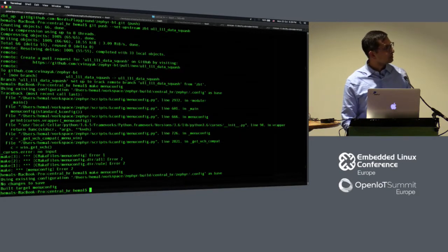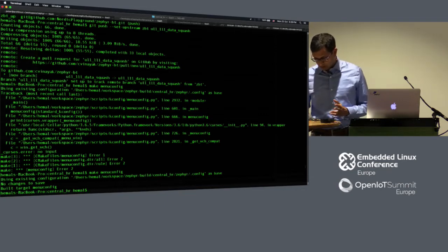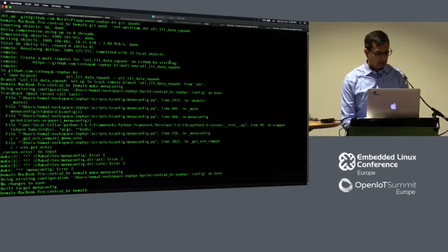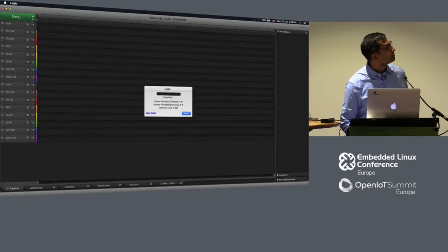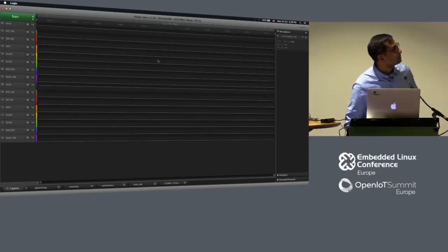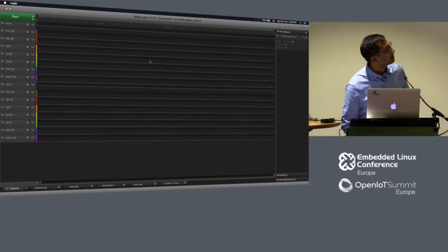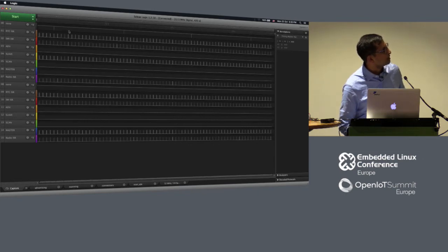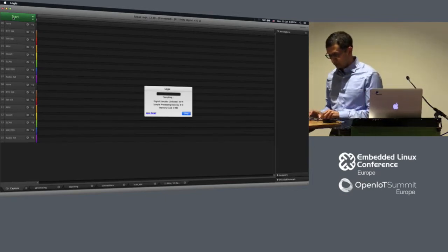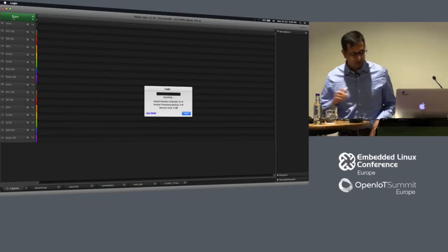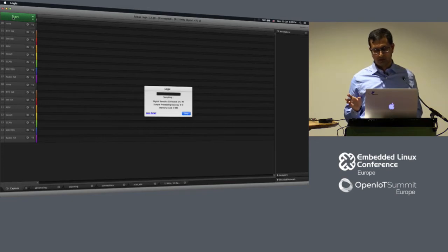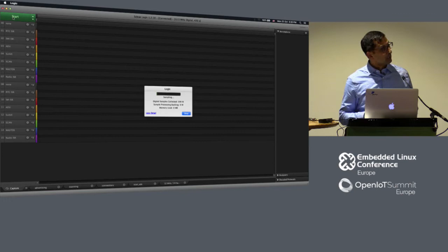So it's already built. I don't know which one is peripheral, but let's see if things are working fine. All right. So I already have a connection. Let me just start capturing this, and I will reset one of the boards and I will reset the other board. So I have a master and I have a slave or a peripheral. When I reset, one of the boards is advertising, and the second board is scanning for it. As soon as it finds the heart rate profile in the advertiser, it's going to establish a connection. So it should have already happened, as I said.